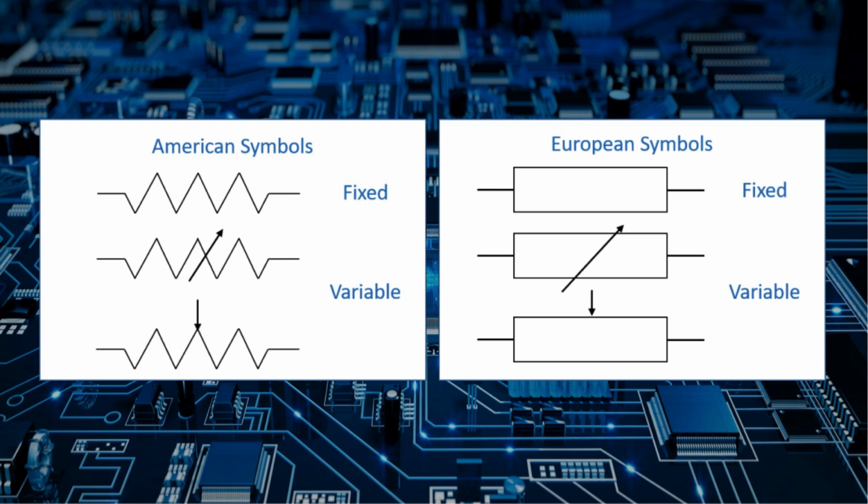Unlike other electronic components, a resistor has no polarity. It can be inserted in the circuit in either direction. Resistors also come in both fixed value types and variable types. A variable type resistor is called a potentiometer. And potentiometers are very useful in that they can be installed in circuits and be used to adjust the resistance in things like volume controls or when doing calibrations.